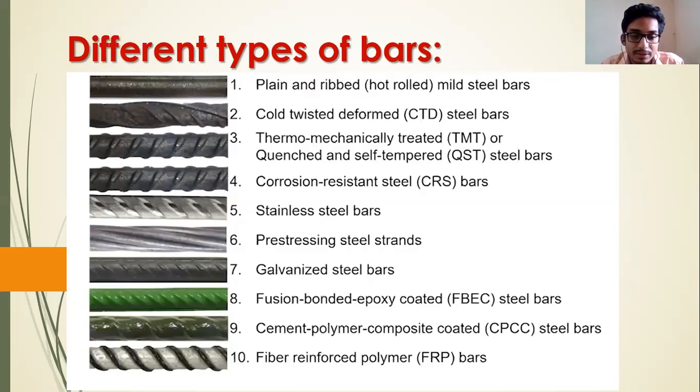In the factory itself we have to have common sizes of stirrups, common bending angles, and common sizes of bars. We should not redo any work on these bars at the construction site. If we do, then the purpose of giving this coating will not be served.